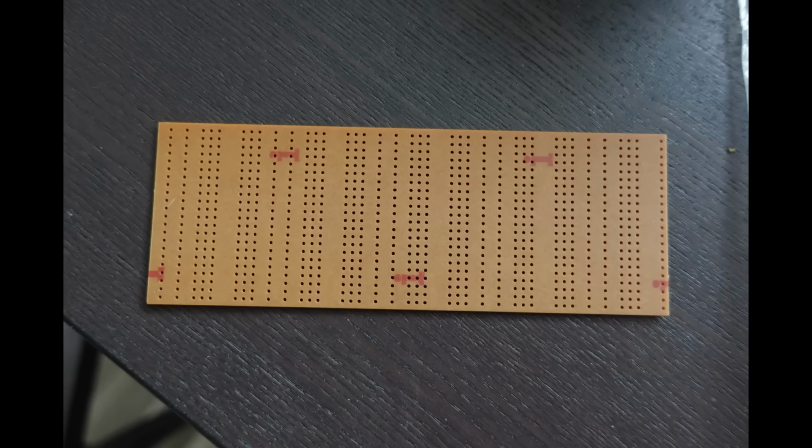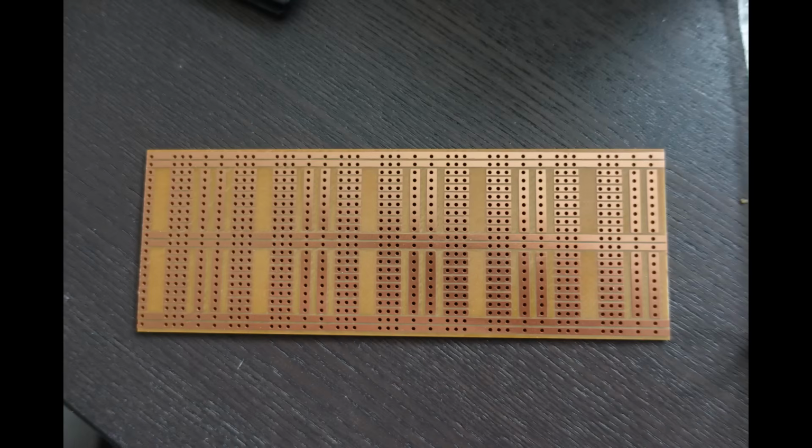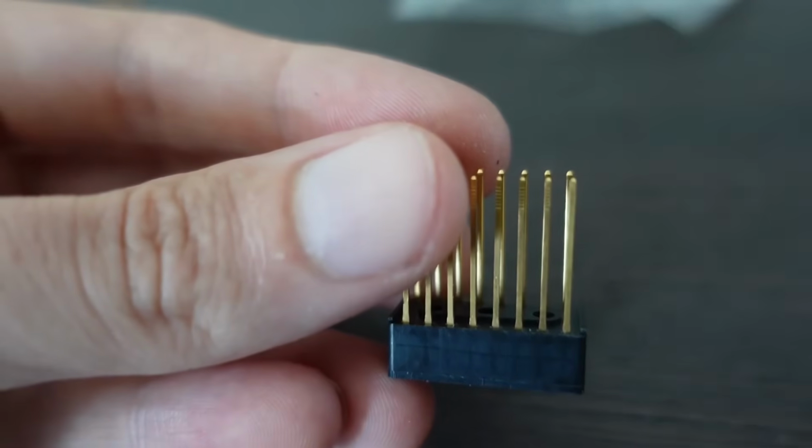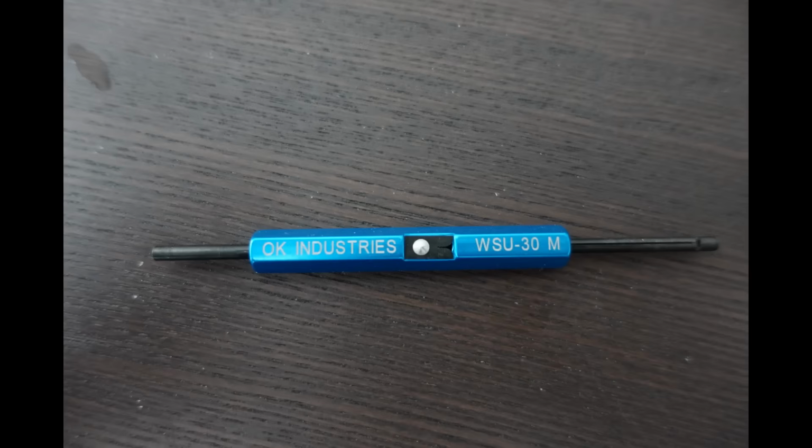If the foundation is a perforated board like this, it may or may not have solder pads. I picked a board with solder pads, so that I could selectively get better access to power and ground if I think I need it. If there's no solder pads, you just glue the sockets to the board. The sockets have these extra long square posts. I'm using a basic hand tool, but there were electric wire wrap guns and automated machines too. With this I use 30 gauge wire.